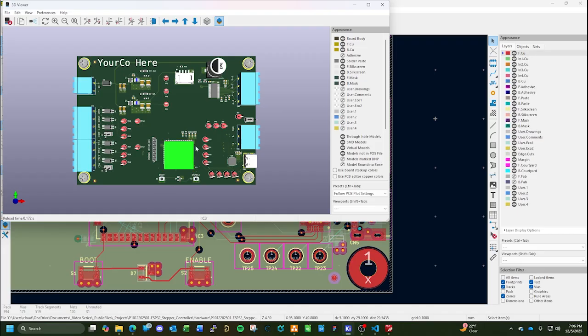Yeah, we should have plenty of room to tie an IPX antenna to the ESP32 with those test points. Again, we don't have to populate them with these. We just leave them as holes and tie into them. That way nothing interferes. We could just populate test points on the first small batch of boards we build for our initial testing, basically our qualification testing. We can leave it at that and then not populate them in the actual release version. For one thing, it'll save money and other things. Reduce the complications of the build because they are through hole parts. So that's what we can do.